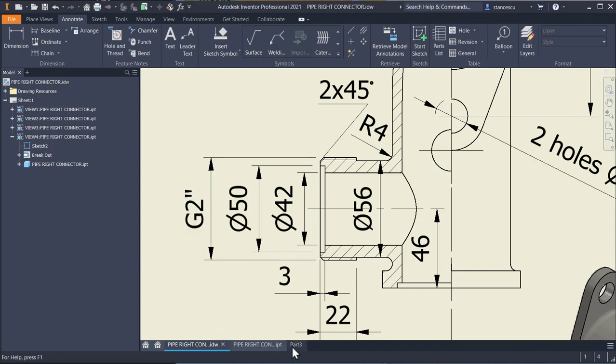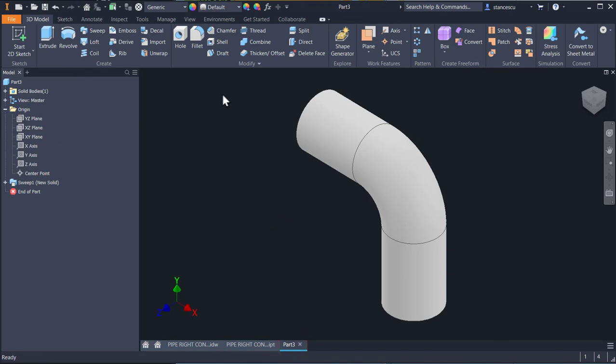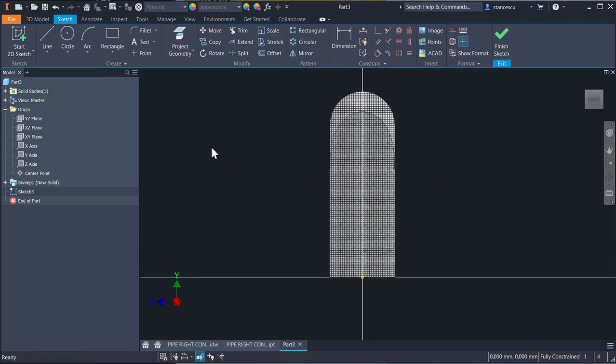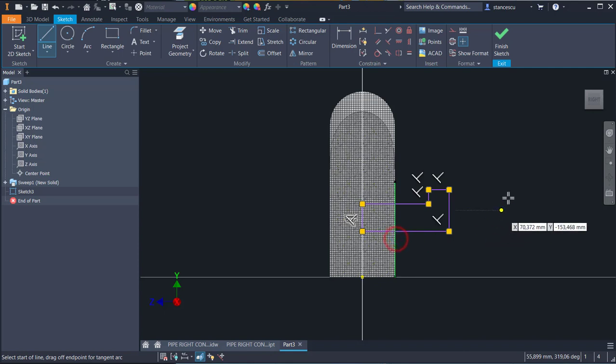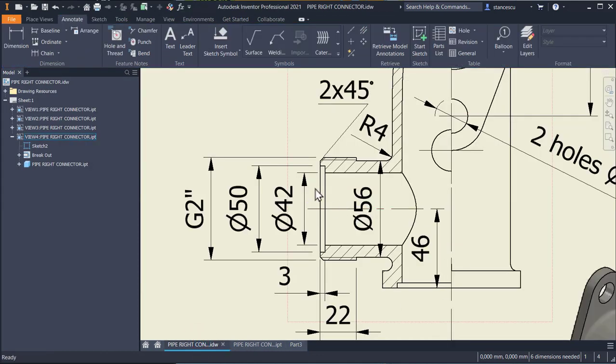Then let's go back to creating a sketch in this plane, F7, with a contour, this contour, close, which is this, to the middle, 46, 56, the diameter for thread, and 22 for the moment.